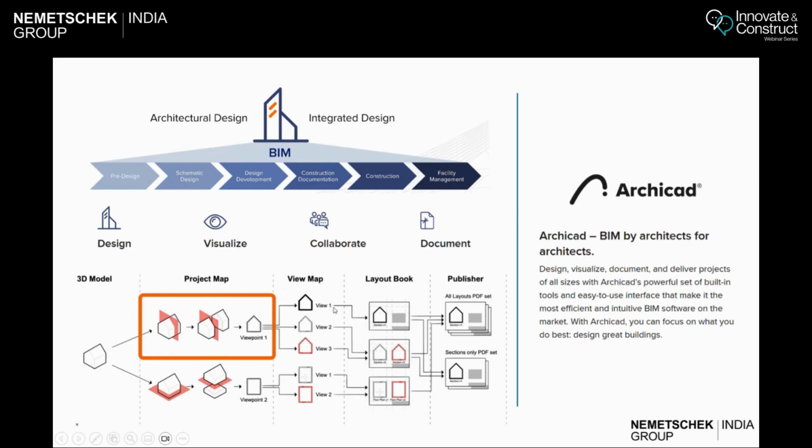For example, I can have multiple floor plans based on one ground floor. Like one will be my furniture layout, and one will be my electrical layout. So in such cases, I can create multiple views based on my viewpoint. And then I'll have my layout book where I can drag and drop all my views to create a